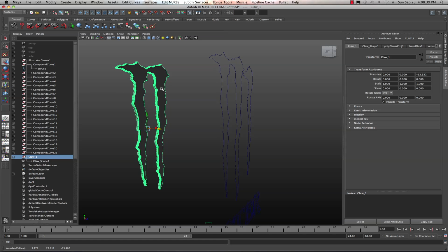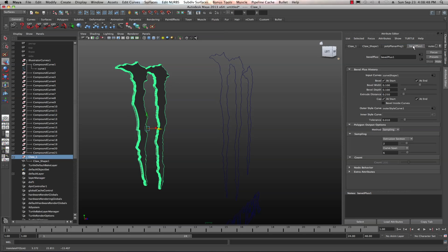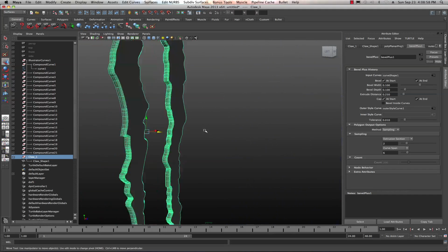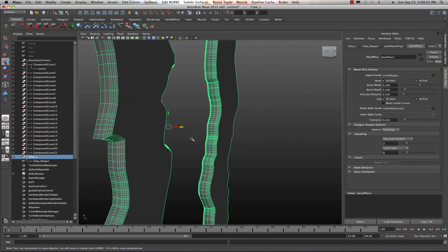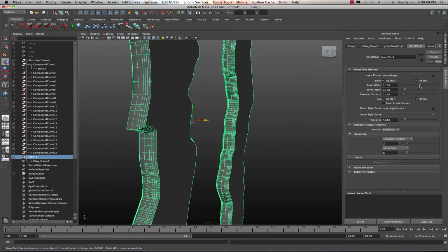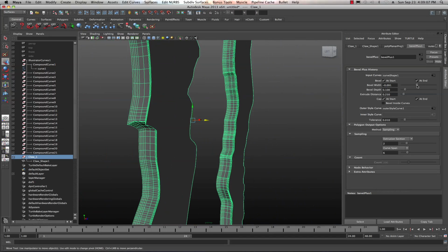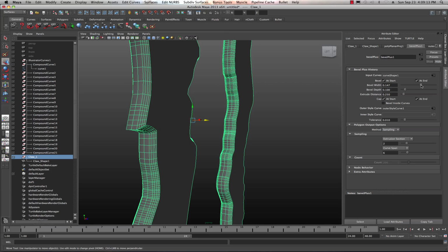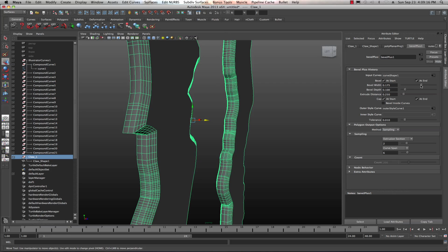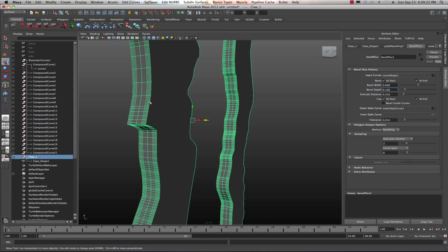Now, one thing that we're really concerned with here as we get started is the object itself. You can see over here we have the Bevel Plus 1 that we applied in the attribute editor here in our tabs. So if you want to mess around with the bevel width, I'm going to bring this a little closer here so we can see what's going on. Okay, bevel width, if I set this down, I can go down in size. It'll start to go into a negative number and sort of recess itself. Or I can bring it out to make it out like that. In this case, I think I'll just do a bevel of 0 and make it completely flat.